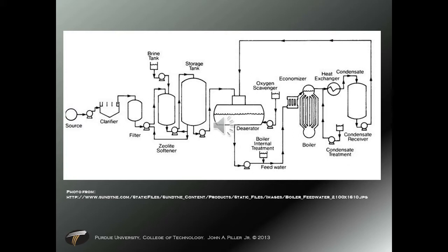The deaerator also takes in clean feed water. But let's talk about the deaerator before we get to the clean pure water purifier section. The deaerator removes gases. It allows settling of the feed water. We don't want gas dissolved in our water into our boiler, into our turbine. It can cause corrosion in there.